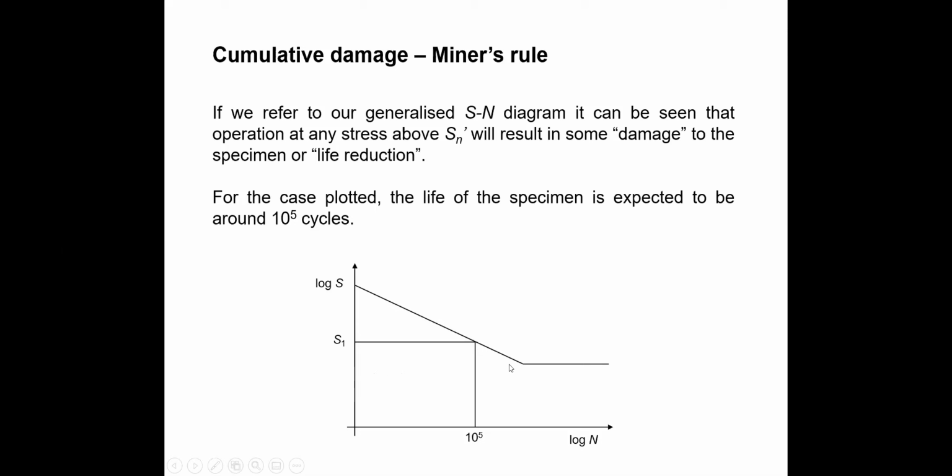So if we apply a stress range higher than 100, you can't apply that particular stress range until infinite fatigue lifetime. So it has a limitation. You can find the equation. You already know how to find the equation of this curve. If you can find the equation, you can find the S coordinate, that means the number of cycles.